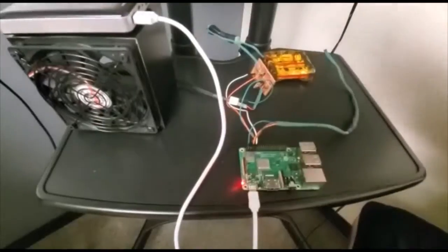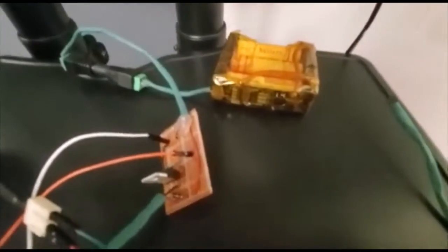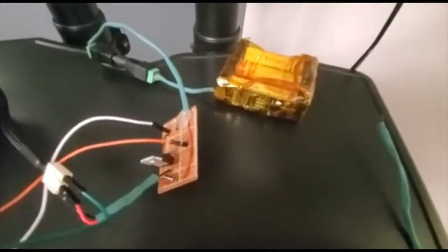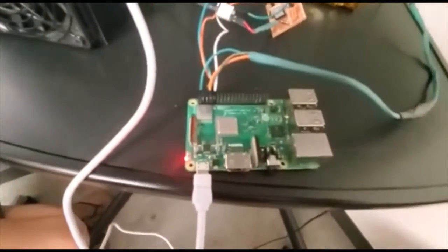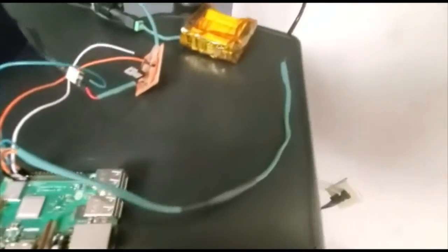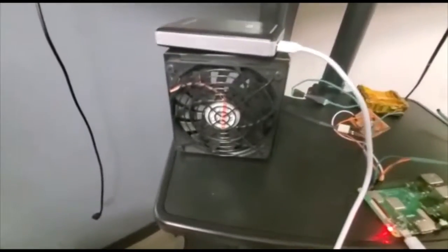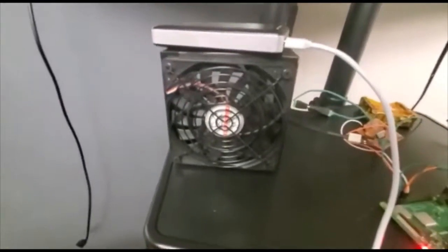Pause it. This is our simulated AC system. For our power supply, we have three 18650s with a battery controller powering our transistor switch, sending this information to the Raspberry Pi. Another input we have is this temperature sensor. The Raspberry Pi controls our output, which is the fan, and this is varied by PWM.